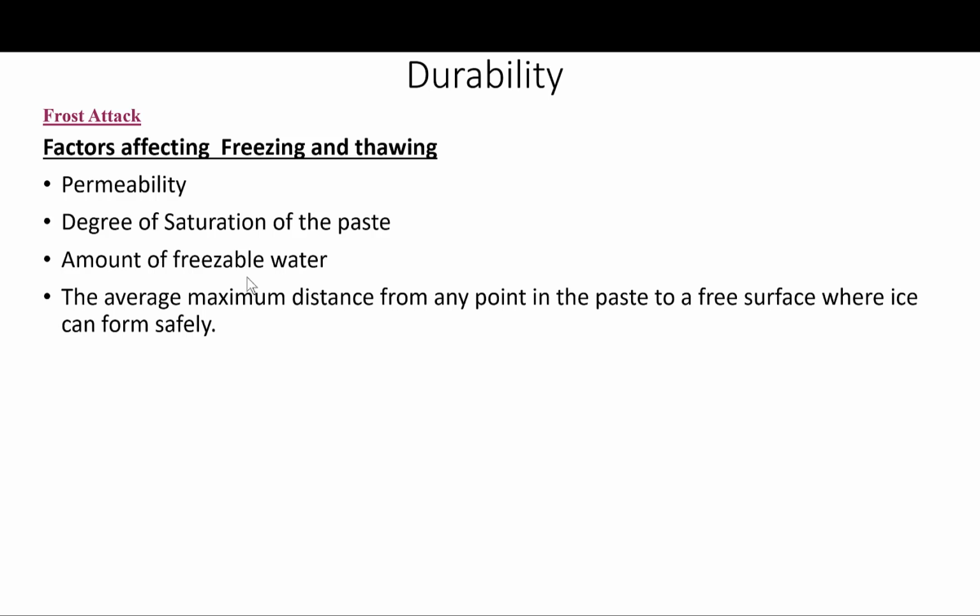Partially dry concrete will not suffer freeze-thaw damage because the larger capillaries are empty and provide the necessary free space throughout the paste. Air entrainment is required for protection only for concrete that is frozen in near saturated conditions. The entrained air bubbles do not readily fill with water except when the concrete is immersed for long periods of time. Once the air bubbles are filled with water, however, the concrete has a greater amount of freezable water and will become highly susceptible to frost damage. So the presence of moisture is of great importance here. We have to be careful about that.